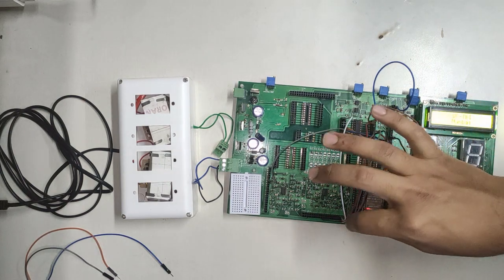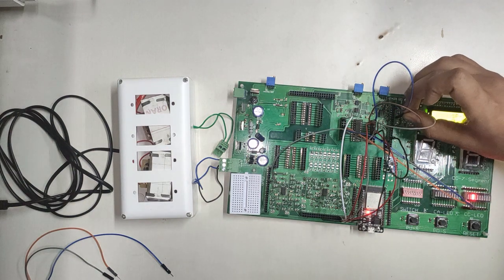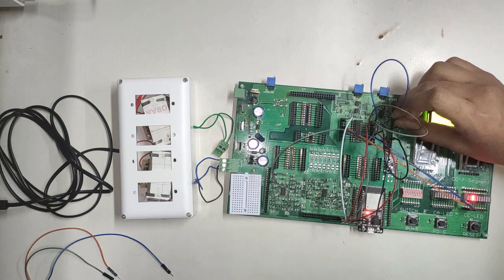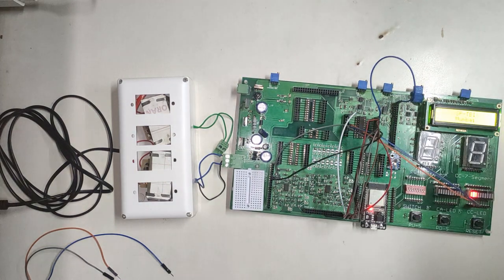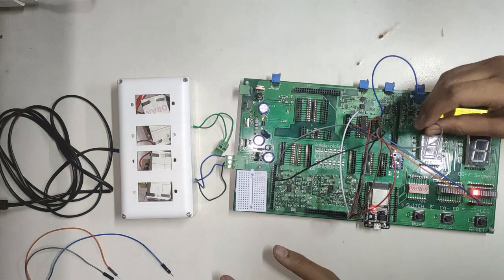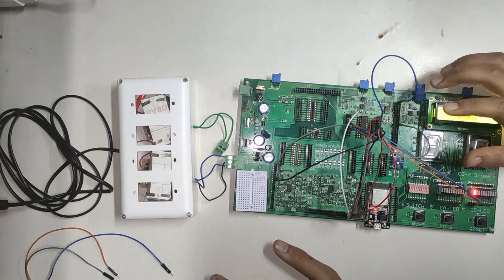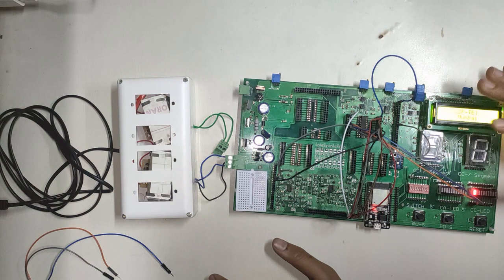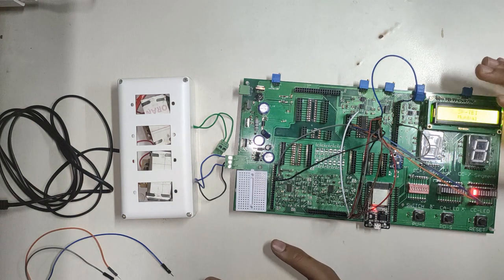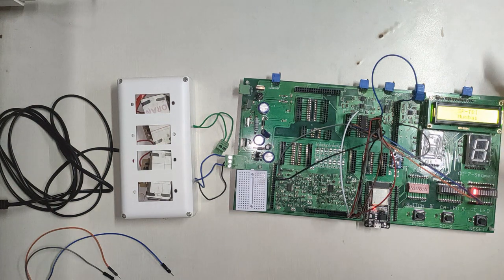Now go to the next case, which is A0 greater than B0 and all the others are 0, or basically equal. Let us try the next case, which is A0 greater than B0. The gray wire here indicates A0. Let us connect it high. For this case, A0 greater than B0, the output is OA greater than B. So you can similarly verify all the other conditions given in the truth table. On verifying the 4-bit comparator, you can also try a 5-bit and even an 8-bit comparator.